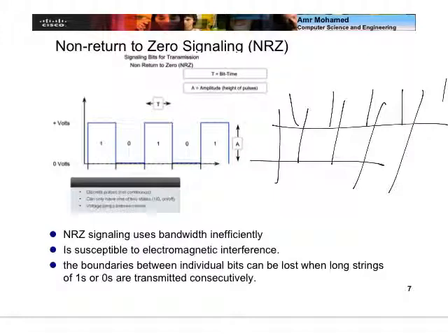Okay? If you have a change of amplitude within each bit, then the receiver can take this change of amplitude as a verification step, to say, okay, I have one change of amplitude here, so this is a separate bit. Okay? So even if the receiver has any clock drift on its side, it can recorrect itself through this amplitude change. Because it recognizes that since I have an amplitude change in this bit, then the other amplitude change must be a separate bit, and so on. So it resynchronizes its clock back and eliminates any clock drift on the way.